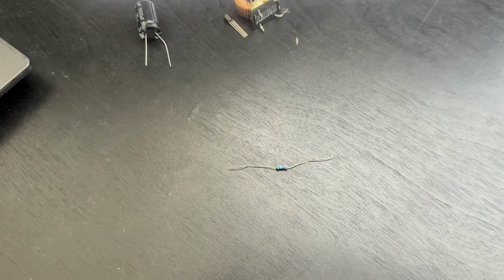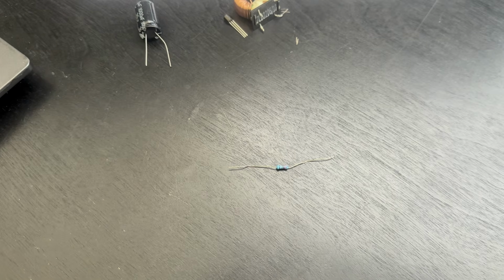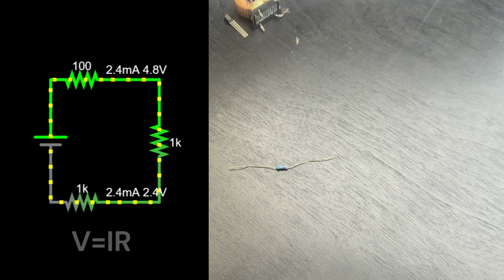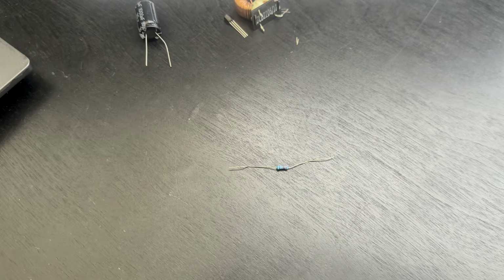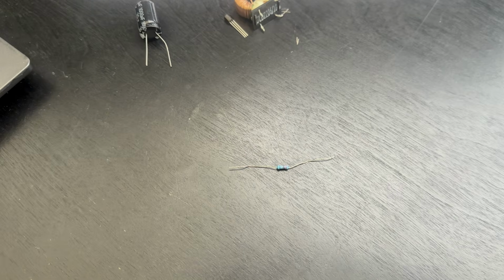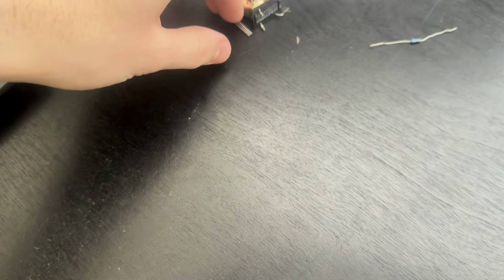So a resistor pretty much just limits current, and it can also limit voltage within an electrical system. So let's look at a simple circuit first, which is a voltage divider. Current and voltage and resistance all have a relationship called Ohm's law, which is voltage equals current times resistance. And we can use this to manipulate our electrical circuits so we can decide how much power a certain component of the electrical circuit can get. And that's what resistors can come in handy with. Next, let's go with transistor.